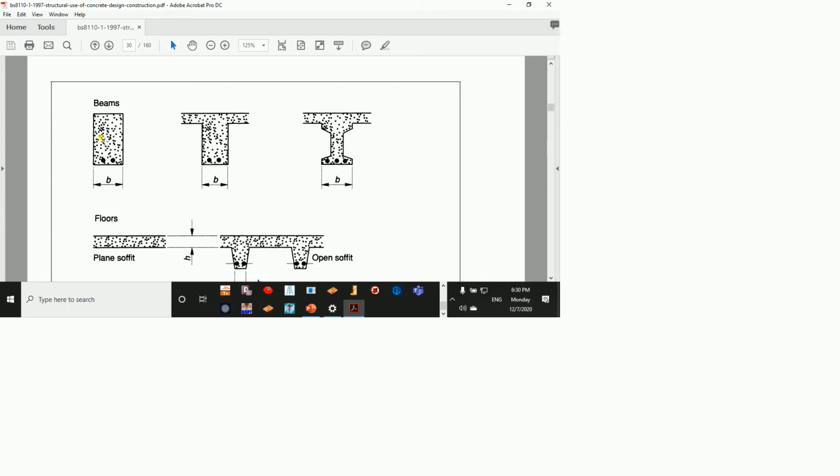this is my remote. Okay. Now, if fire is available all over, which part is going to be easily burned? The smaller one or the bigger one? Smaller by common sense, right? So when you are talking about the critical part here, in case of a beam, it's the width, not the depth. That's why they have only considered the width. And if you see the software, it says the width. It didn't say the depth.